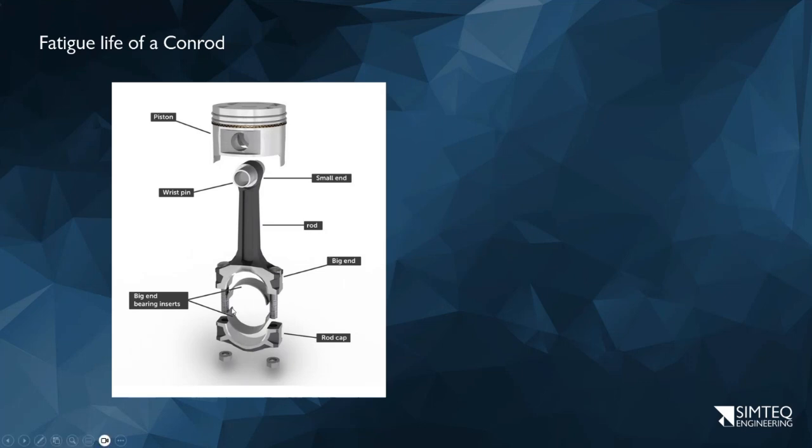But in addition, our load level also changes. So if I have part throttle or we're fully coasting, there's very little compressive stress other than, again, due to centrifugal loads. But the moment we have any kind of wide open throttle conditions, there's a significant change in compressive loads as well. So if I want to calculate the fatigue life for something like this, I have to specify at which speed and what kind of a load level I need to do.